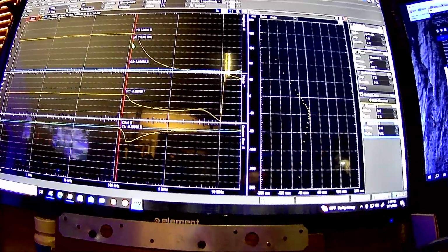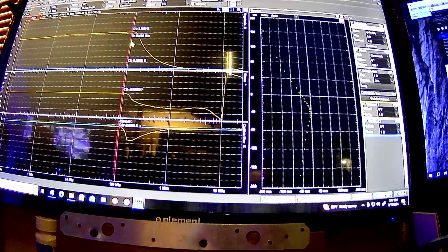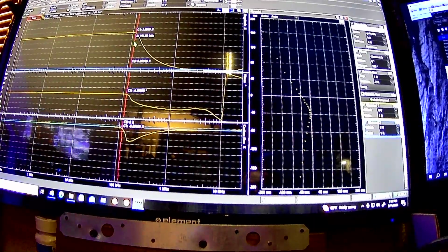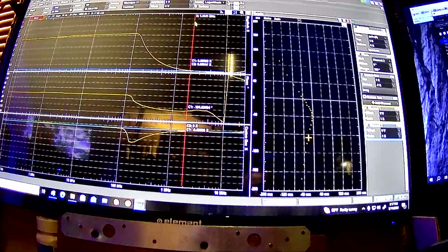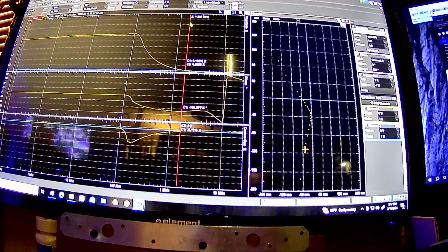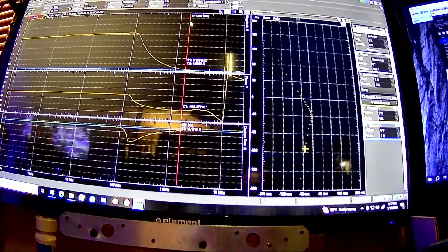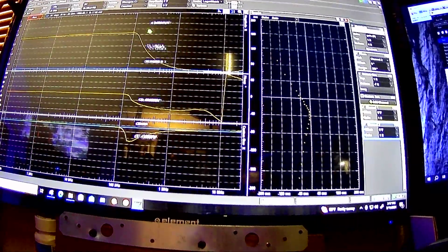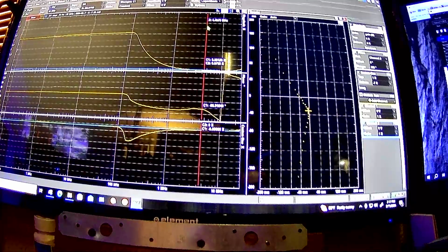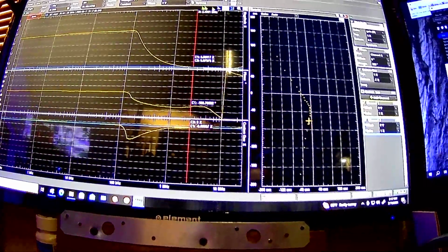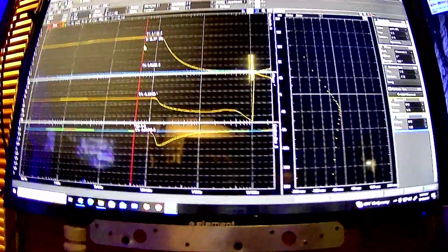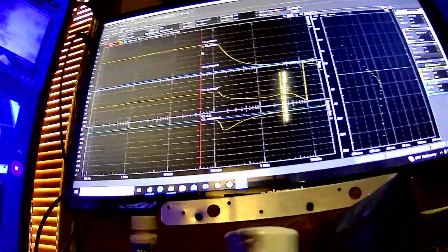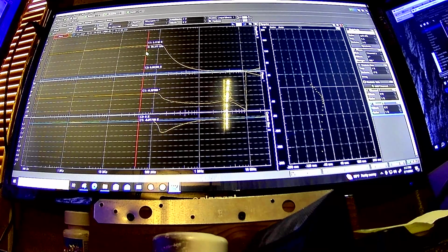Okay, but yeah, it's gain of 3 out till about 117 kilohertz at that level. But again, that's going up to like the max. Yeah, it's 24 volts peak to peak. But at any rate, that's how to check your power bandwidth basically. So you've got to kind of pull the thing, and again, it's a pretty useful tool,